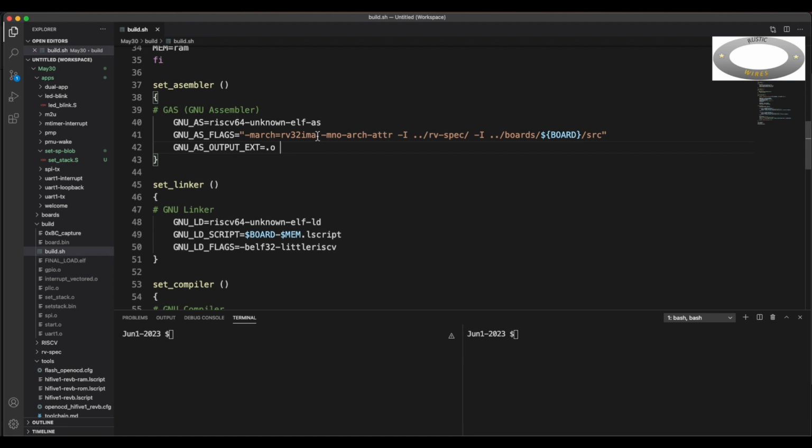Since I did not add the C flag, though the hardware FE310 supports compressed instructions, since I have not enabled it in the march, all the instructions that have been generated by the compiler would be 32 bits wide. So now directly when you pass this to the assembler and compiler, this is how we do. However, when you pass the flag through cargo, and you know that cargo has the